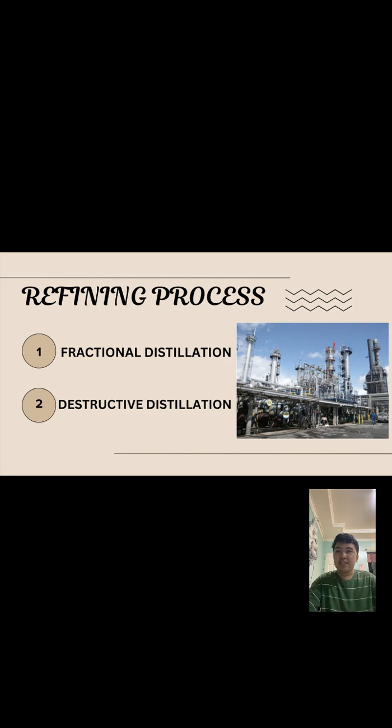The steam distillation is a continuous process in which crude oil is either pumped through tube stills or processed in batches. The temperature is gradually raised to evaporate different components at a specific boiling point, and tube stills, preferred in modern refineries, are more efficient than batch processing.